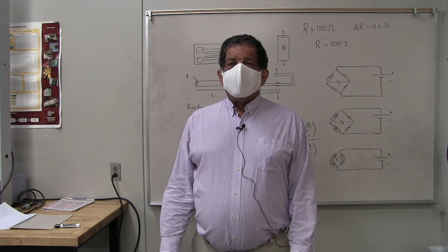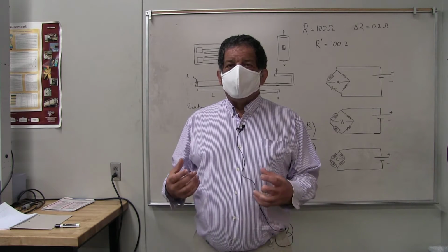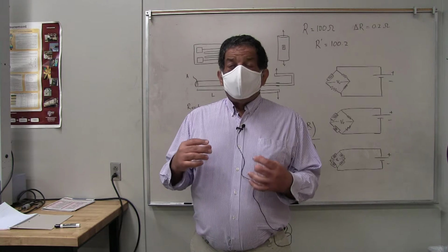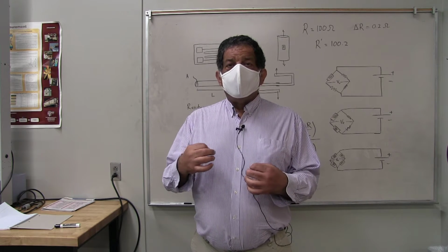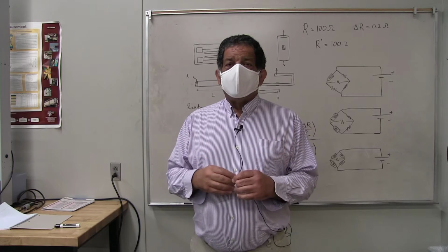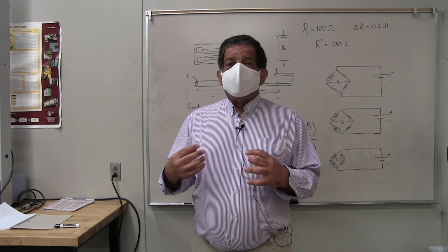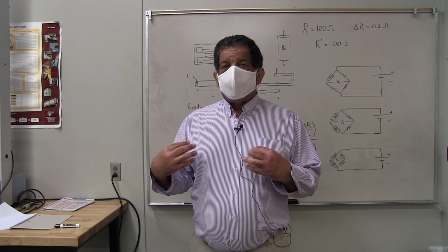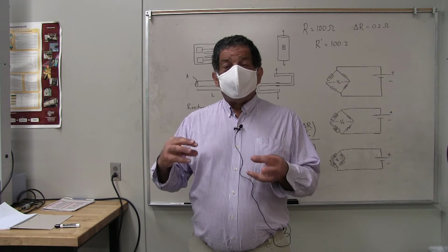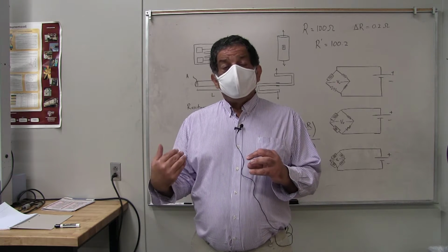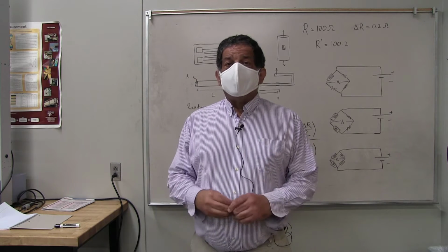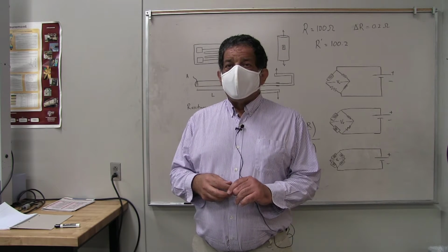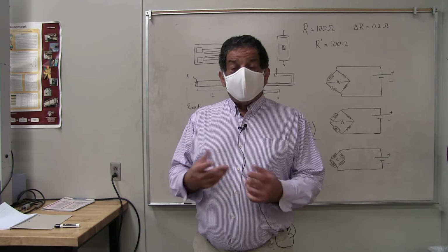The other common technique that we use to measure forces is to apply the force to a deformable body, to a spring. And then if you know the cross-section of the spring, and you know the modulus, and you know your strength of materials theory, then you can calculate for a given applied force or moment or torque how much that deformable body is going to deflect. So if you measure the deflection of the deformable body, you can deduce what the force was that was applied. And that's the theory that we're going to be using in the measurement of the strains that we are going to have on our cantilever beam today.